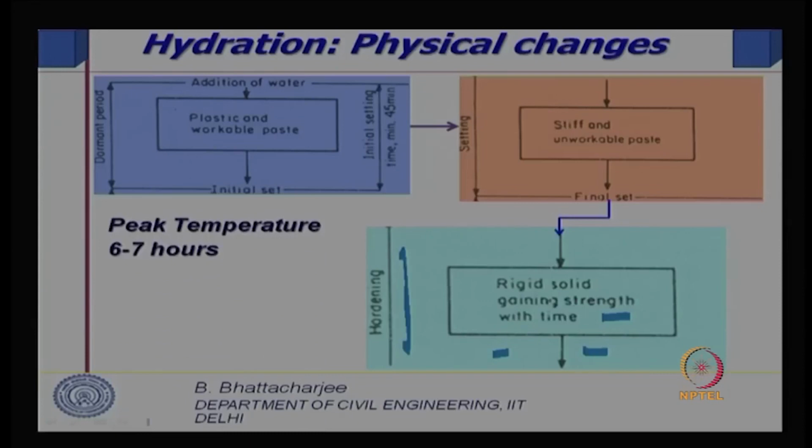Well, peak of temperature occurs 6 to 7 hours after mixing the water, and final set generally corresponds to about 10 hours or so, not more than 10 hours, that most of the codes will specify.